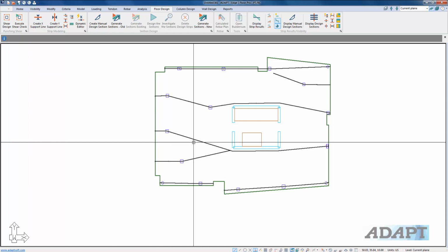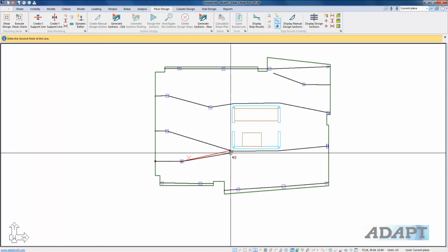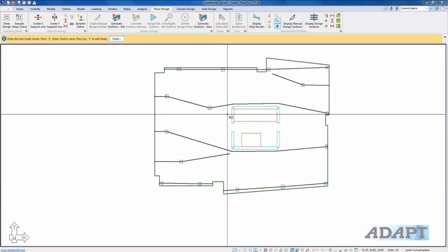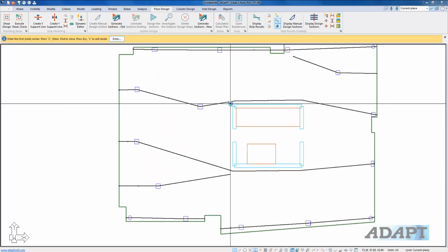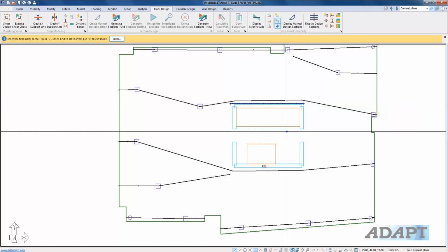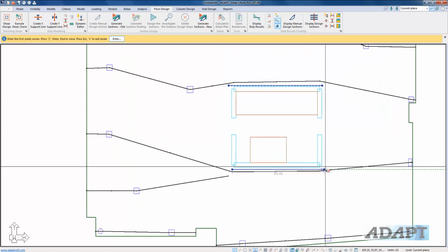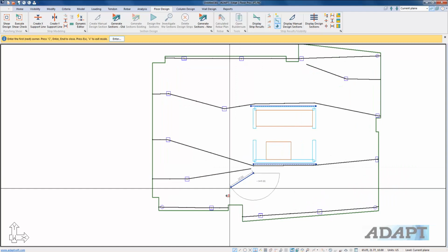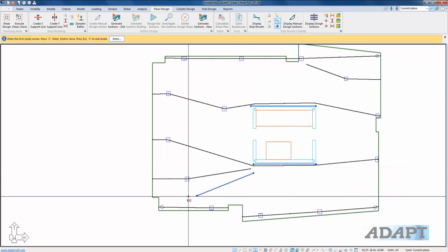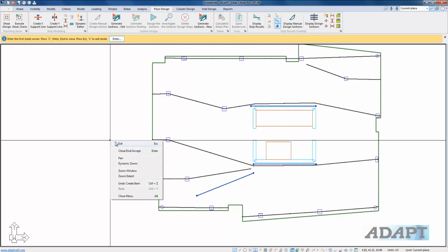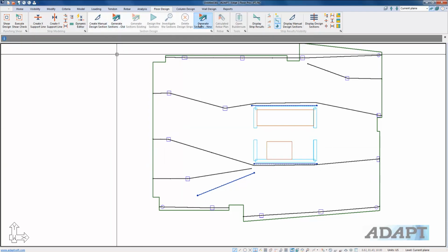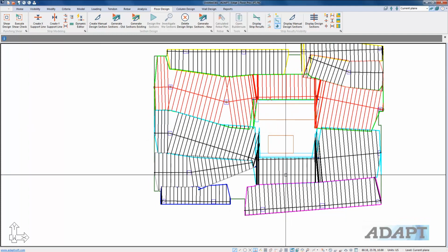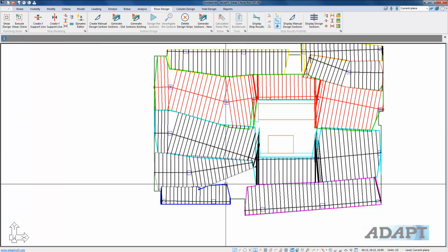And now I'm going to generate the requirement for splitters, which are really now boundaries. So I'll use an X splitter, and I'm just going to create a boundary along that path. And I'll create another boundary along this path. Maybe I want this to be something like that. And we'll go ahead and generate again. And you can see this cuts the strip off from entering this region, and the same thing here.